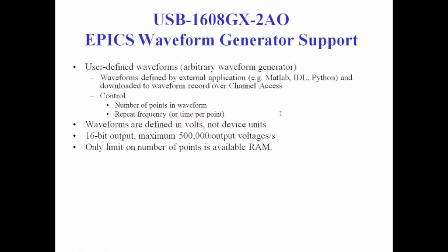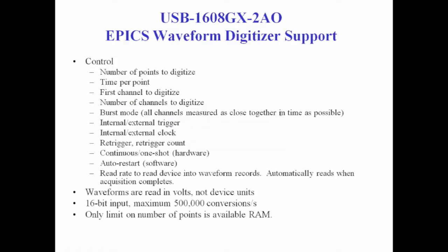So you could define your waveforms in an external application like MATLAB or IDL or Python and download them in a waveform record over channel access, controlling the number of points in the waveform and the repeat frequency. The waveforms are defined in volts. It's a 16-bit output, and a maximum is 500,000 samples per second. And the only limit on the number of points is the available RAM.